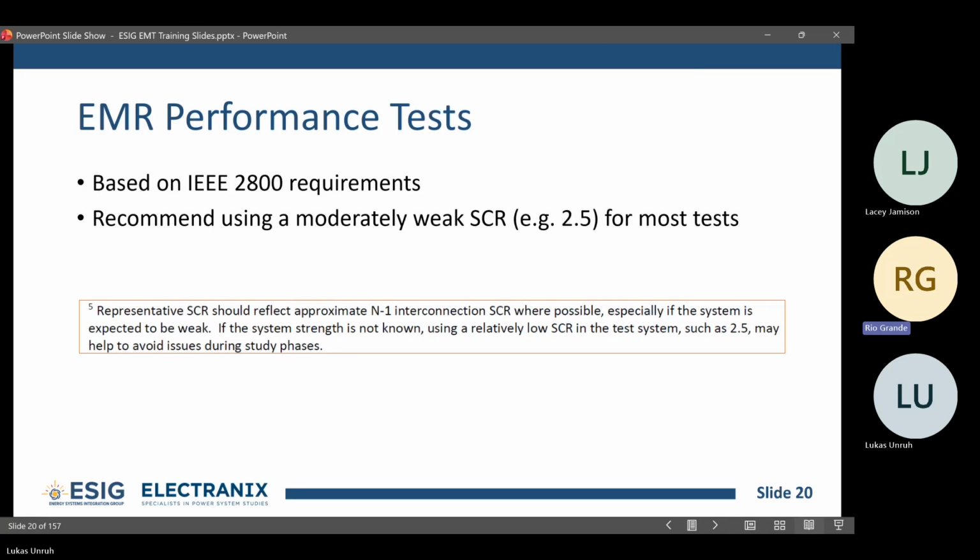But for a weak system, the sensitive factor is for sure short circuit ratio. And the utility should be able to get you the X/R ratio, which is much easier to define compared to system strength. So that should be a much easier number to get from the utility for a given connection point, in my experience. So one person uses 5, the other uses 6. Well, yeah, that's the ballpark of what I normally see in cases, but yeah, it's a good question.